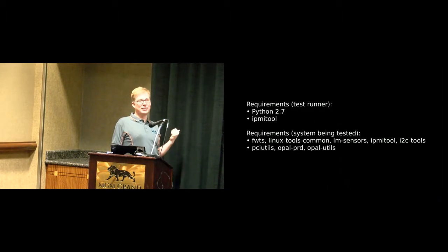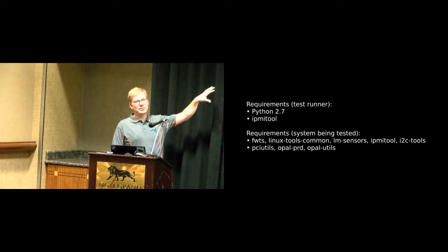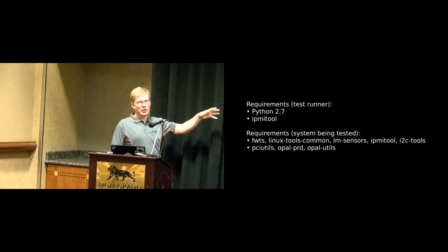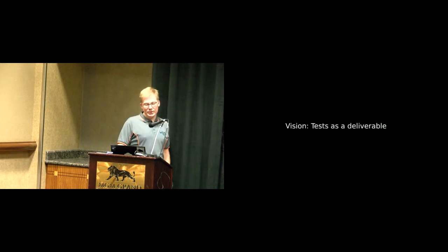IPMI tool, let's do as much over using the binary IPMI tool that everyone's going to use to interact with these machines, even though it would arguably be more efficient to have a pure Python IPMI implementation. No, let's use the actual binary. On the systems being tested, let's just use a bunch of standard distro tools. Let's poke using a normal FWTS, which is from Canonical, they use for firmware tests. We use the PCI utils and I2C utils and standard sensor utils,